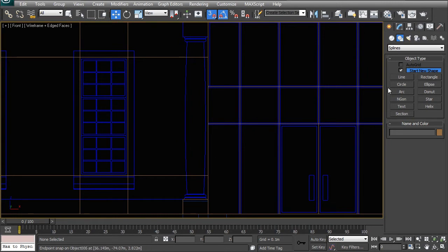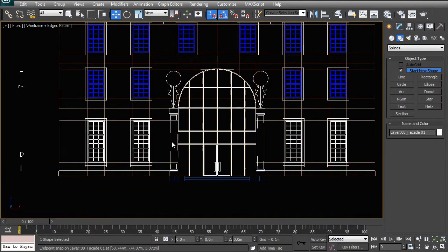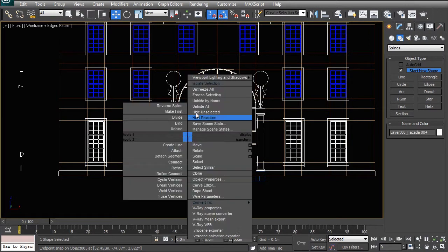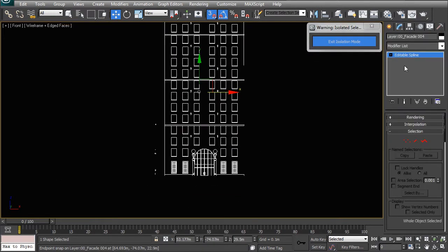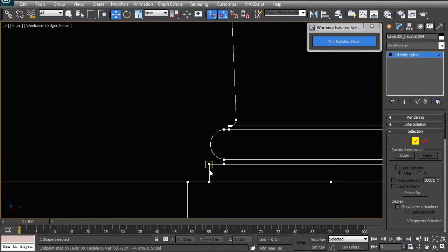Now one way you could do it is that you could manually draw and redo the arcs and radii, or you could actually take the CAD geometry, and just like we did before with the roads, with the pavements, we could just go Control V, make a copy of it, isolate that, and then just go and extract those few lines that you actually want.